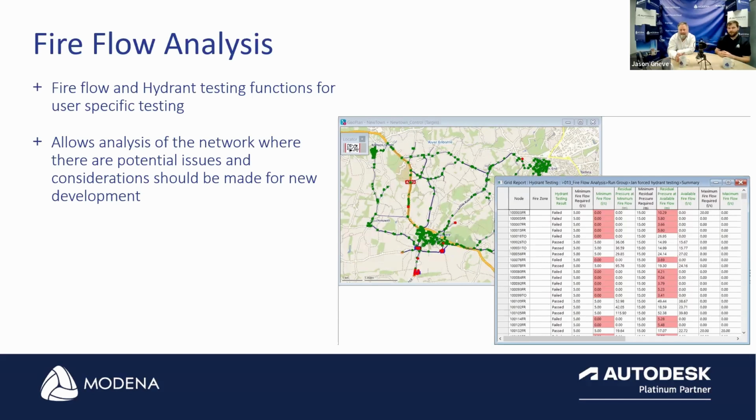Next up, we now have the fire flow analyses. So this little screenshot over here that I want to show you is actually one of the scenarios that was run within the simulation on the cloud. In the scenario, we had a bit of a master plan, and we had close to, if I'm not mistaken, 1,000 to 1,400 fire hydrants. And we wanted to run different scenarios to say, all right, we want to have one fire hydrant firing throughout the entire process. So it went and checked each hydrant individually.